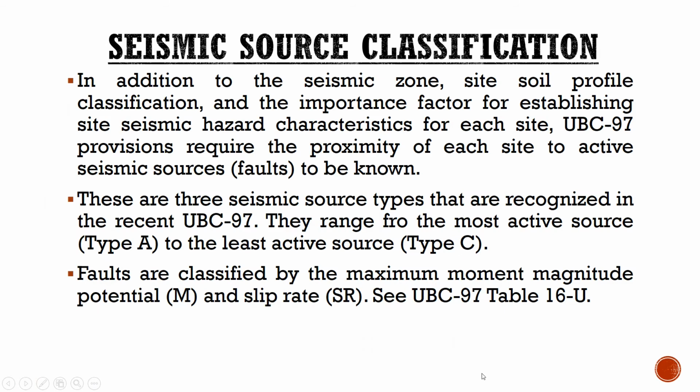Okay, so seismic source classification. In addition to the seismic zone, we have the site soil profile classification and the importance factor that were established by UBC 97. It also requires the proximity of each site to active seismic sources or faults to be known.